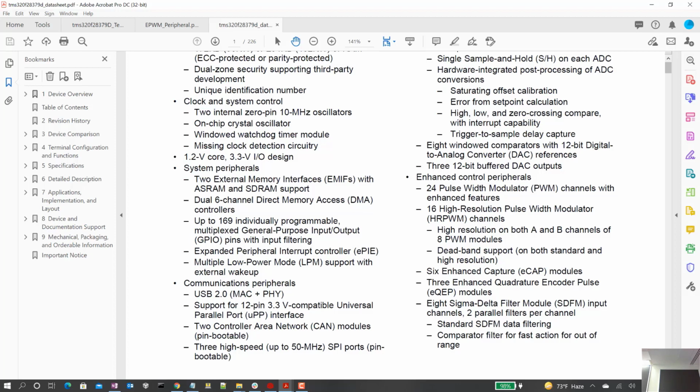But when you see all these different peripherals, you've got to remember that you cannot necessarily get all of these at the same time out through your I/O pins. There's multiplexing going on inside the processor. Each pin has up to, now most of them are only about 6 options, but they have it set up for maybe future chips with a possibility of 16 different options going out of one pin.